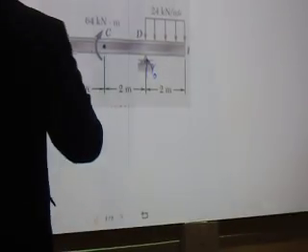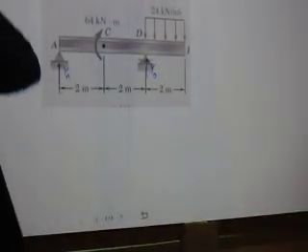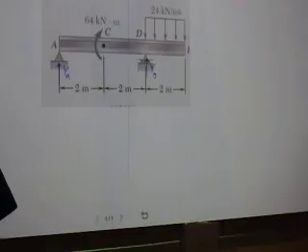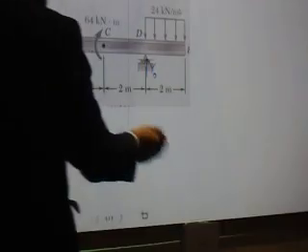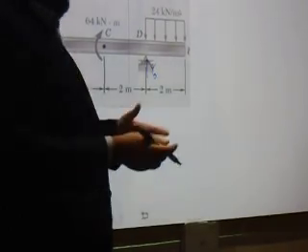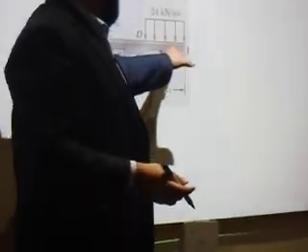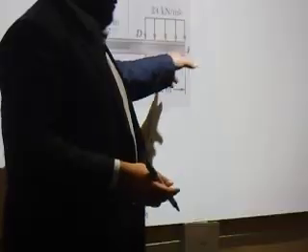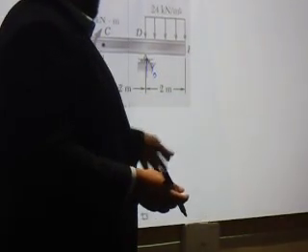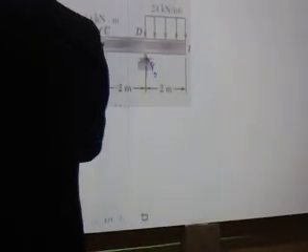First step, I say, okay, sigma moment about D to get YA. Why did I take it about D? Because YD will be easier. Because here the centroid is very clear, this centroid is in this direction, and there is nothing else other than this direction, and this moment. So sigma moment about D, I'll get